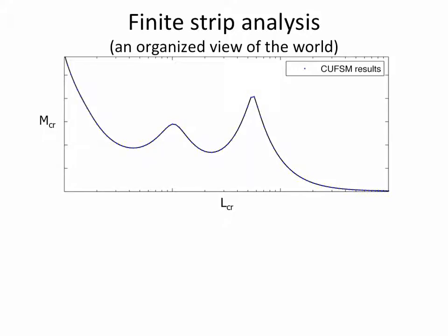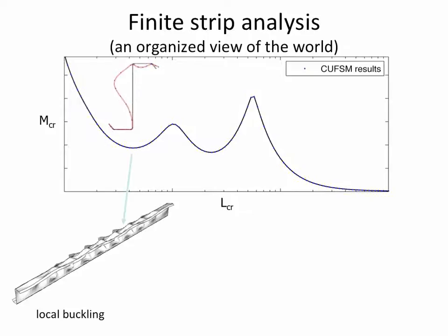All right, and so how do we get the parameters? There are equations for calculating Mc for lateral torsional buckling, flexural torsional buckling, and flexural buckling, pi squared E over L squared, and then you have the J's and Cw's floating around in S100. So that's this part of the curve.